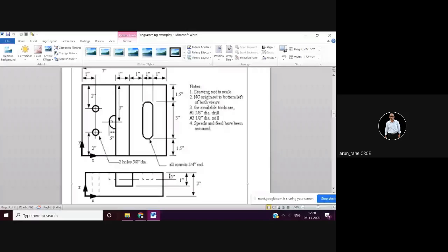So you have to give this point. Then you have to give this point. Give this point, then this point, then this point, and then come here. After coming here, now here your Y is how much? 3.5. The cutter is going like this, okay. Then it will come out here. Now let us take the cutter a little out. So instead of saying Y exactly 6 inch, we'll say Y 6.3.